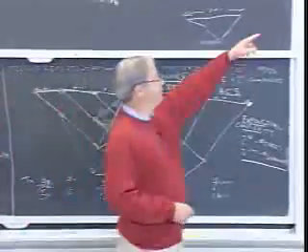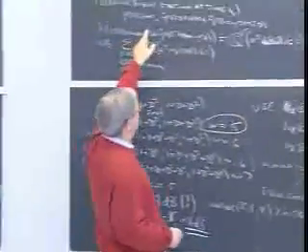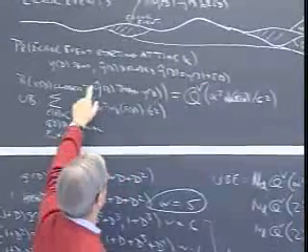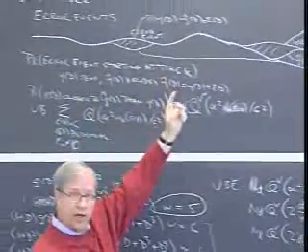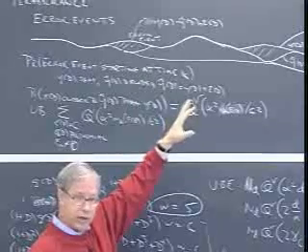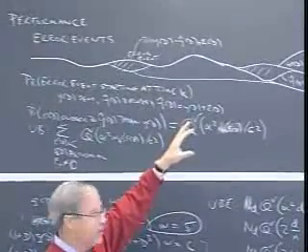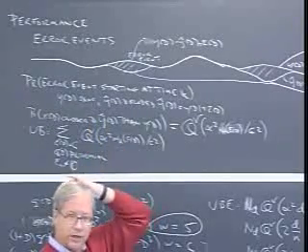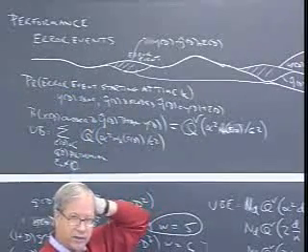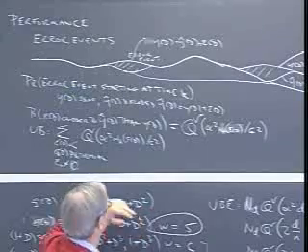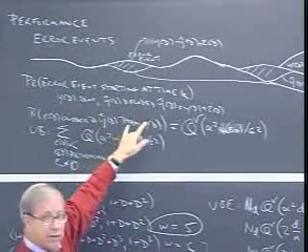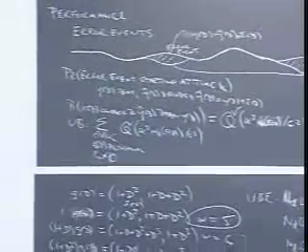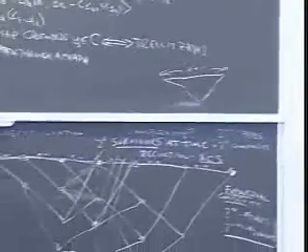I've defined an error event by taking a transmitted code word. It's a code sequence. This is supposed to represent some path through the trellis. There's a 1-to-1 correspondence between code sequences and trellis paths. Then I find another code sequence, which is the one I actually decided on. I call that the decoded code sequence. And I say, what's the minimum length of time they could be diverged from one another? All right, let's take this particular trellis.